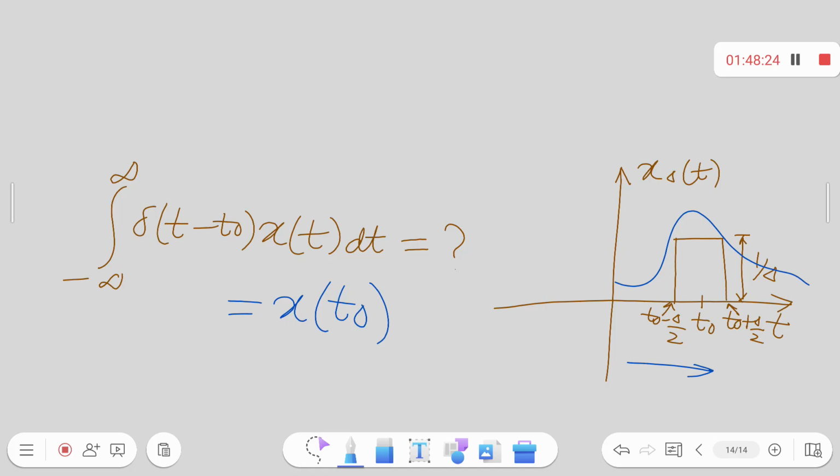So these are the different types of signals that we have considered so far. Typically, the exponential signal and the sinusoidal signal. You know that the sinusoidal signal can be regarded as a component of the complex exponential signal. If you have the complex exponential signal, then the x coordinate and the y coordinate will give you the cosinusoidal part as well as the sinusoidal part, as in the phasor. And then some typical functions like the step function, then the ramp function, and obviously the delta function. These are the basic functions with which we deal in the next few classes.